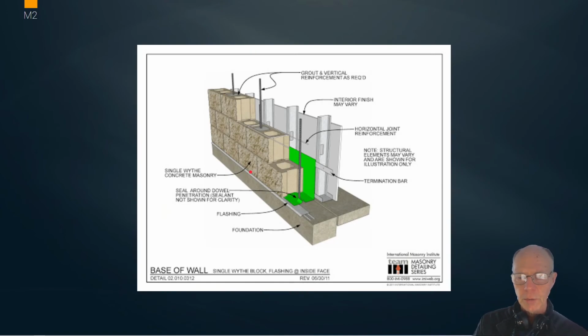And here's another example of a detail with a wall constructed on it. I'm showing you these because they're references that I can grab off the internet. I would invite you to look at them, and they really contribute to a much better understanding of what happens at the detail level of the things that you start to build, and the need for what elements are missing. For instance, as green is a flashing detail, that any water that would get between the two would be directed to the outside of the building.